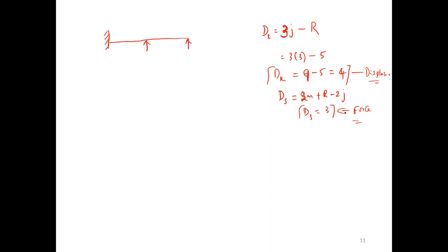See, I still remember we have given 4 statements. Because the static indeterminacy is less than the kinematic indeterminacy, in that case the force method is preferred. If I go by the displacement method, here I am not getting 4.